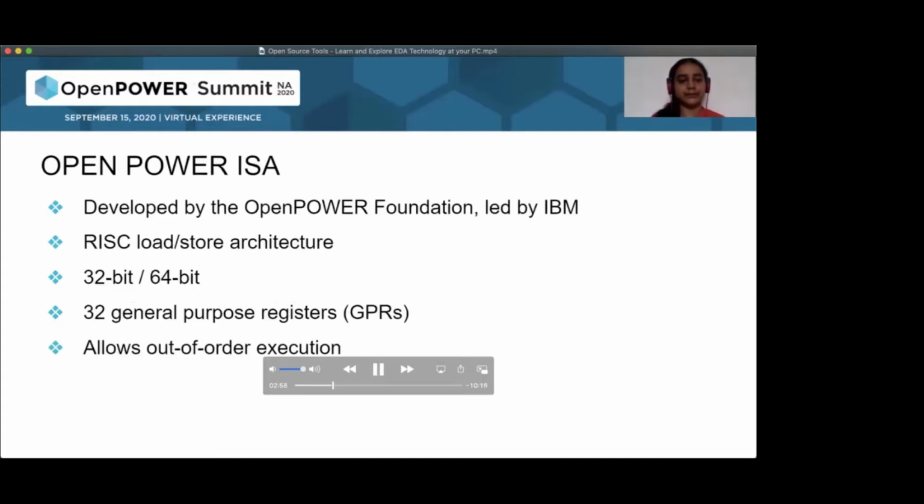So let's move ahead. First of all, discussing the OpenPOWER ISA. Why did we choose this one? Because it is an open source ISA, which means that anyone can freely take it up and design any hardware, maybe a new microarchitecture description or anything else with the ISA. And they can freely use it to design and study more about it. It is a simple RISC load store architecture. However, it has highly specific instructions as well, which are mainly designed for vector multiplication, addition, and the same applications for floating point numbers or maybe integers. All those operations are there.